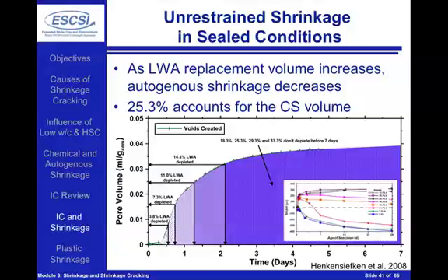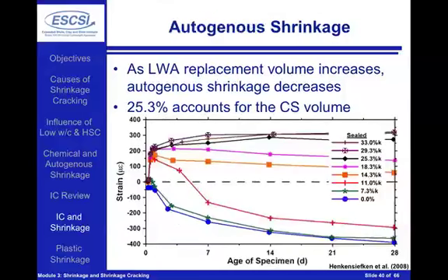And here's a graph that shows these different amounts of lightweight aggregate that would have been placed in the system, and where we'd really start to see that lightweight aggregate being depleted of all the moisture that would have been in it. So if we look at the 11% case, for example, around a day and a quarter, we see that the aggregate has run out of water that it can supply back to fill in the vapor-filled spaces. And after about a day and a half, in the 11% red case, all of a sudden we start to see the shrinkage picking up.